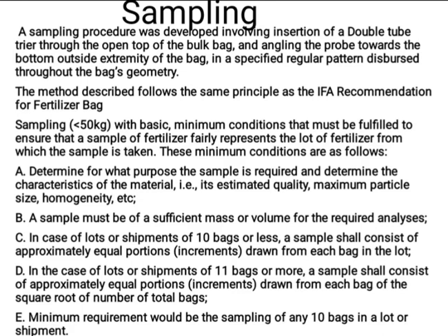This is basic, but if you have to perform large scale sampling in the industry, then you can take at least 10 bags and collect a sample from the top of each bag, from the bottom of each bag, and then mix the samples from all the 10 bags which you have collected from the top and the bottom together, and then you can use this sample for the analysis of the amount of nitrogen, phosphorus and potash. So the sampling can be done for various purposes.